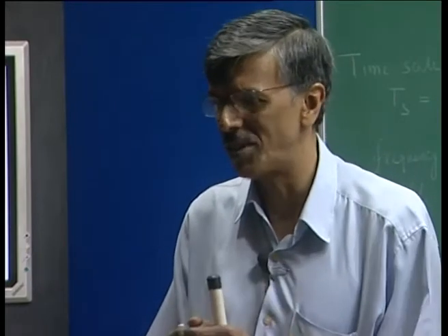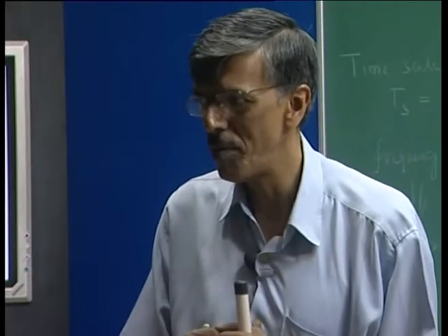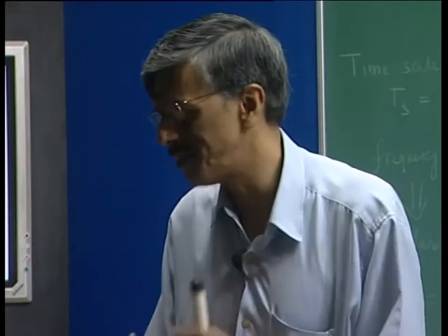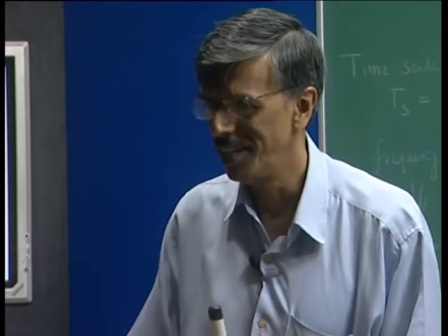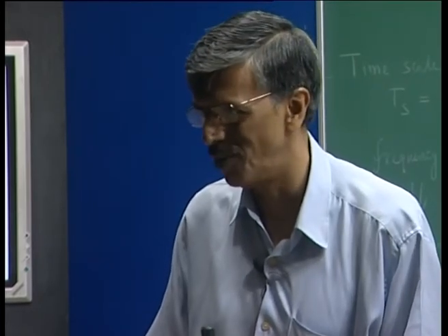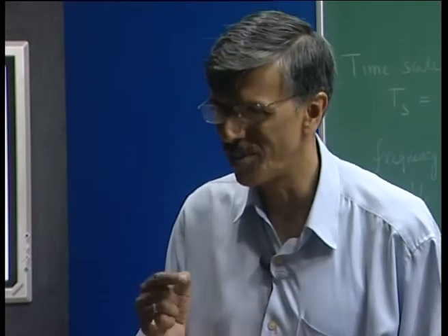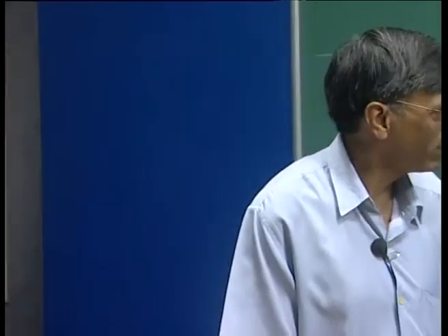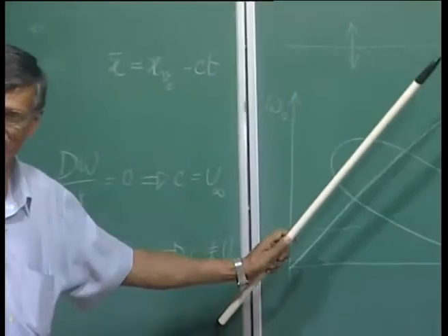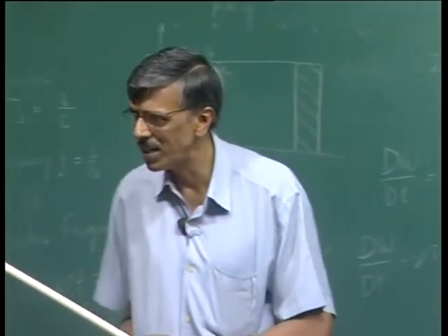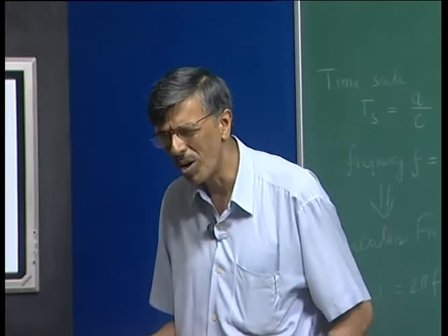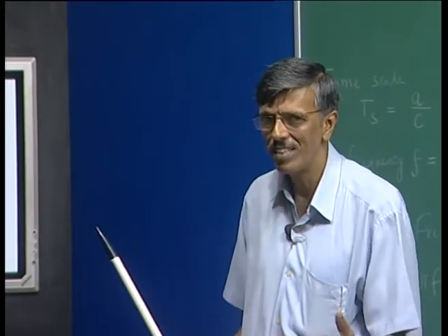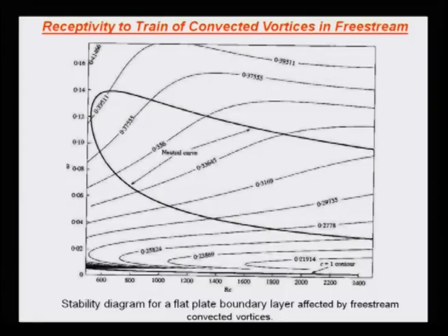So in the end what you get is kind of wave packets consisting of TS waves. We should not have called it bypass, but if we would not have called this a bypass mode, how would we characterize it? We said this is not the usual Schubauer-Klebanoff type of TS wave, but a different kind of TS wave, and we call this a bypass mode of transition. But essentially these are wave packets, created like this. So this is what we must understand.